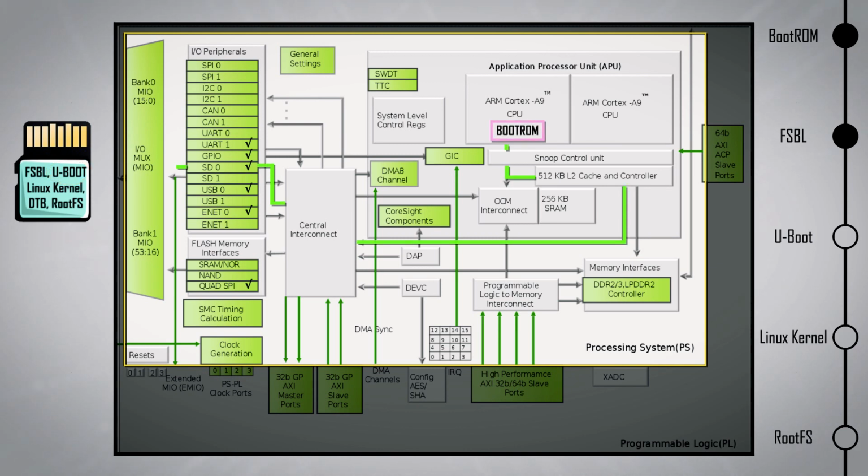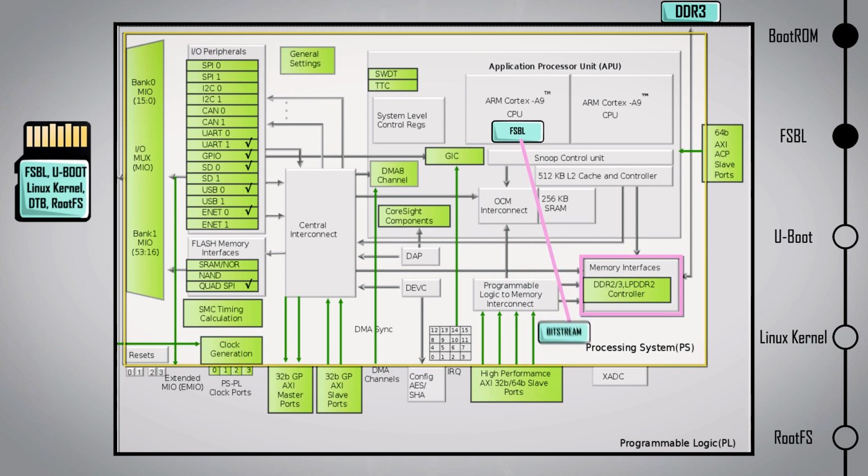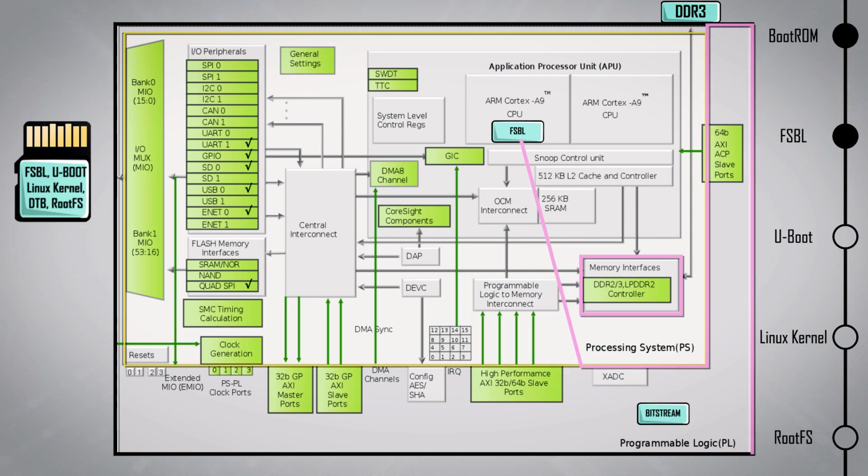When the BootROM fetches the bootloader from the SD card, it really is only grabbing the first stage bootloader, not both bootloaders. Having two bootloaders like this gives the first stage bootloader the opportunity to configure some of the essential hardware needed during the booting process before passing control off to U-boot. This methodology is useful because U-boot or the kernel may not have all the know-how to configure hardware components specific to the Zynq chip. It's also worth mentioning that the first stage bootloader also configures the PL with your custom digital logic if a bitstream file is present. More on this later though.